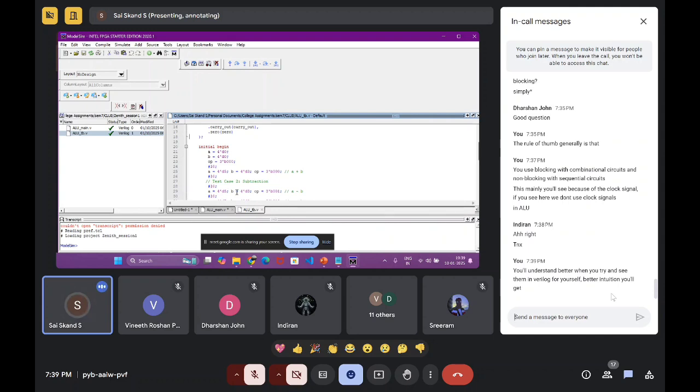Okay, we provide this initial begin. This is another type of block similar to always, but this is okay. We'll talk about this further. Right now, this is just another block that will execute, similar to an always block, regardless of any condition. This will just execute.